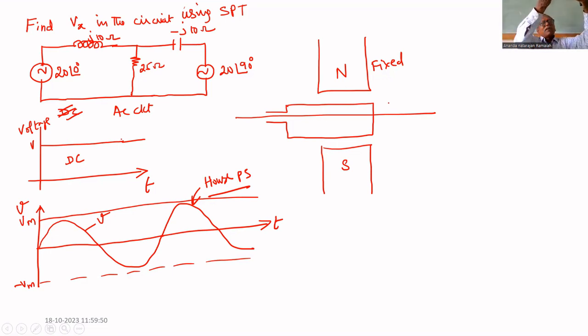If it goes up, gradually voltage increases to maximum. If it comes down, gradually it decreases to zero. That's why it varies like a sinusoid when rotating in the magnetic field. When the displacement is parallel to flux, it does not obey Fleming's right-hand rule at this point, so there is no EMF.